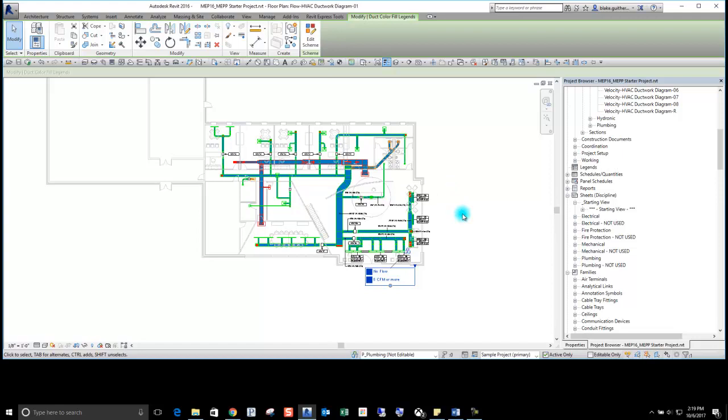It's actually very helpful to be able to use the duct sizing and pipe sizing in Revit, but before you can get there, you have to know that you have the proper airflow in the systems. So we'll be talking about that in this video and going over a couple examples. If you don't have things connected and if you don't have airflow in the duct systems, then using the duct sizer tool in Revit isn't beneficial at all to you. However, for the last 10 years, I've used a duct calculator and a lot of stuff outside of Revit, but now having the information inside just makes me that much faster and more efficient sizing the ductwork.